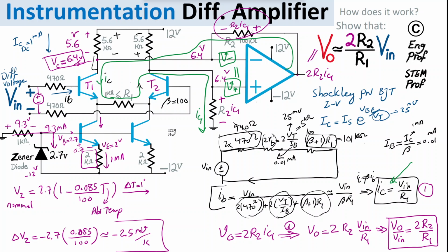On the other side they are connected to the negative and positive terminals of the ideal op amp with negative feedback that enforces that these two nodes are the same voltage. So basically the 5.6K resistors have the same voltage drop, matching. Therefore, no differential current can flow through these two, and the green differential current can only go through the route I am showing in the circuit.